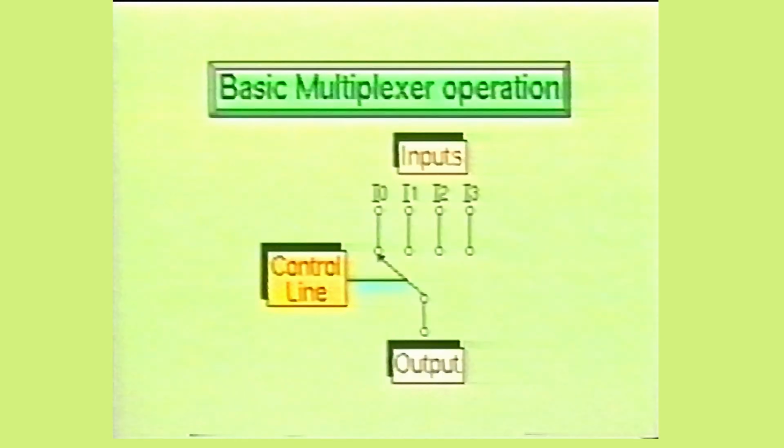The digital multiplexer is a combinational logic circuit containing 1 to 4 control inputs and 2 to 16 data inputs for each data output. Some multiplexers even provide complemented data outputs. Basically, the digital multiplexer performs the function of a single-pole multi-position switch in which one of the data inputs will be connected to the output at any one time. The particular data input being selected is controlled by the control inputs line.